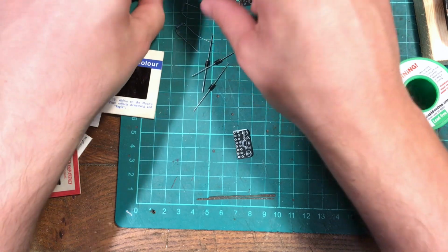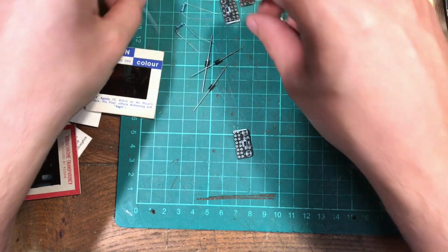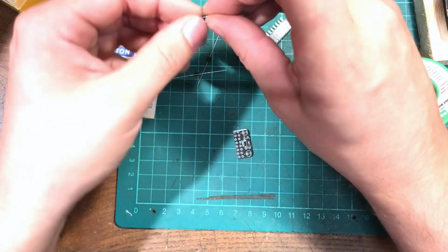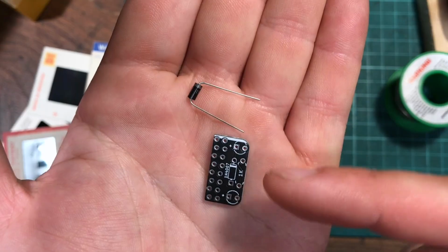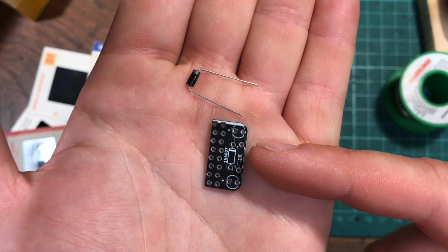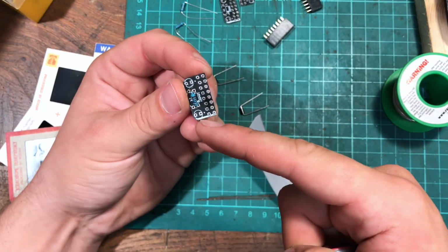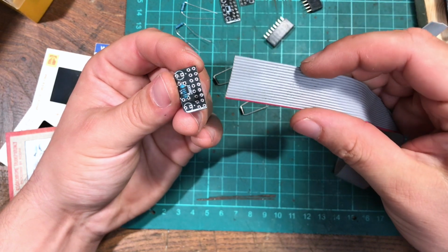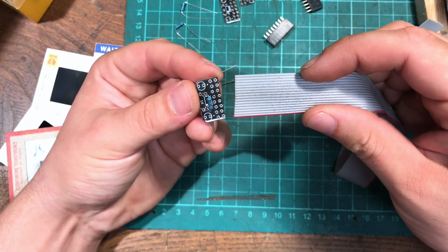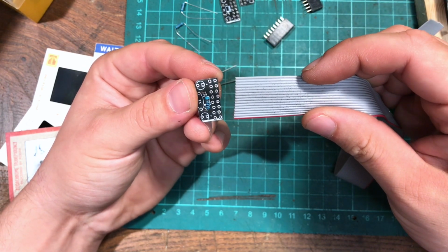Just start with the resistors and the diodes, get them all in there, make sure the diodes are round the right way. They've got a little stripe on them, and that goes around the same way as the stripe on the silkscreen symbol. And the white stripe down here is the equivalent of the red stripe on your Eurorack ribbon cables. So it's just telling you that that side plugs into minus 12 volts.